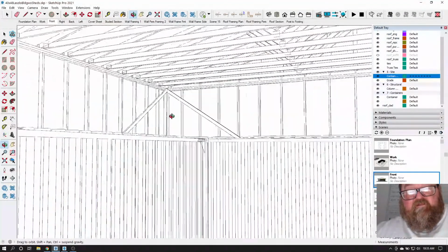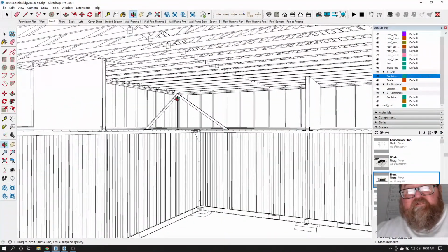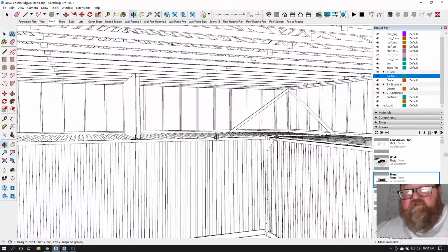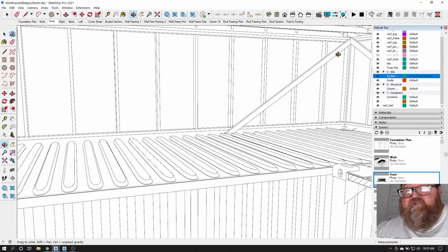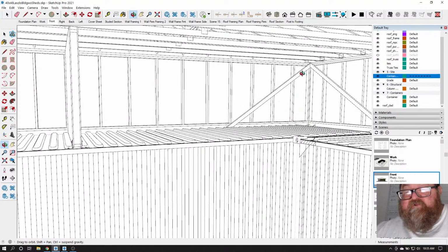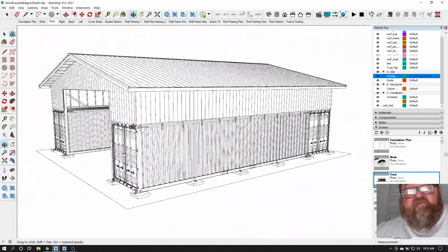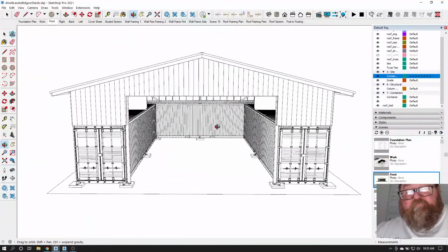Yeah. And see, since this is sort of an agricultural use building, it's not going to hurt. I really just want those braces to be permanent. And that's why I'm showing them with an angled cut on the ends. They're more neatly done. If you were just doing this temporarily, they would be squared off on the ends and wouldn't be neatly done. So I just want them neatly cut and placed and nailed good and left there.